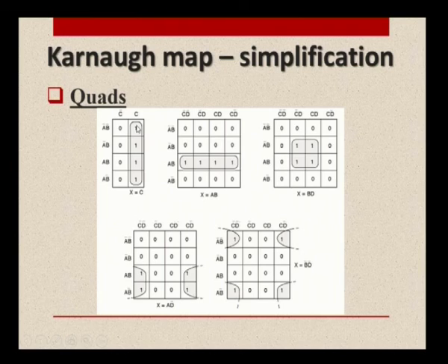Now, for a quad, see, we can have a quad in a vertical line, 4 terms, or horizontal, or even the 4 could be considered as a square pattern. And here also, as I said, the rolled table will also have the quad formation. The quad could be taken in the 4 extremes also. It is like you fold them horizontally, also vertically. In that case also these 4 terms will come together. So, in any possible manner we should be able to recognize a quad in this way.